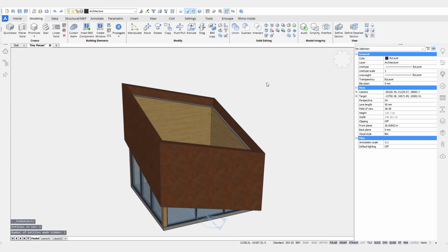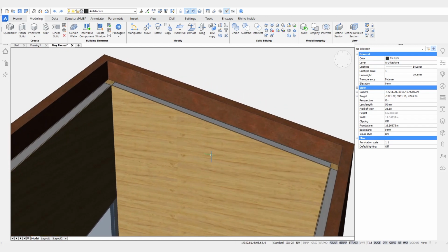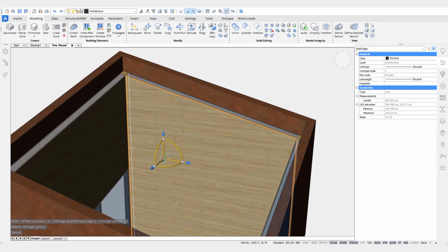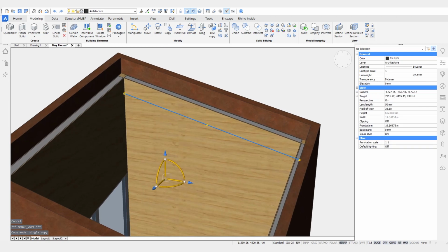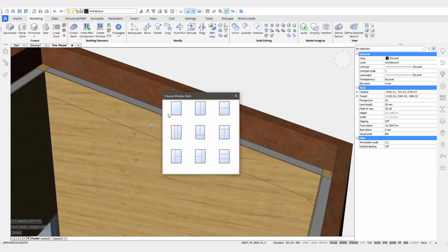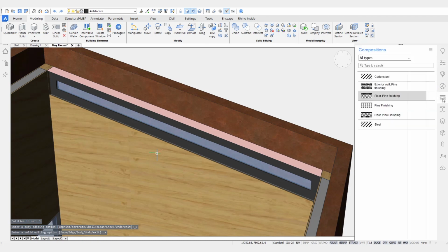I also had an idea of having a window over here, so maybe on the inside of the building it's easier to see. A long narrow window along the top here. And again, I'm going to use the same technique of just creating a boundary, and again using this window create tool to create this trapezoid window. Now obviously, we won't be able to see anything through this window because we have this shell in the way. So I'll just model this hole as well.